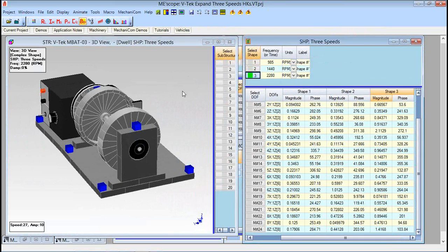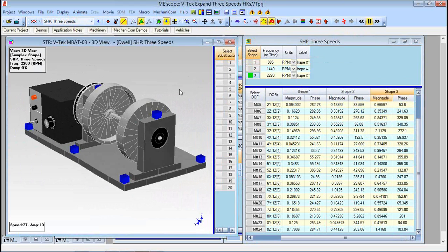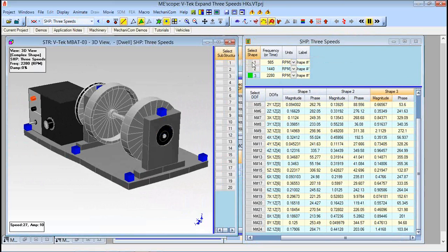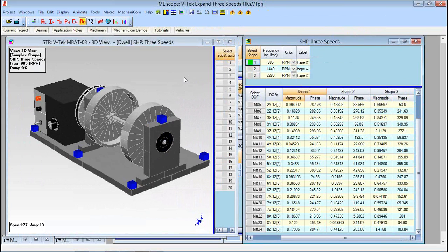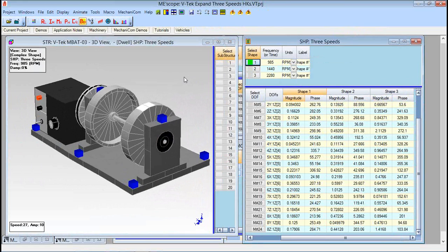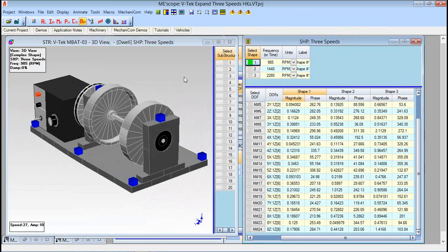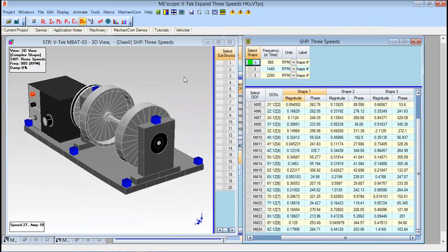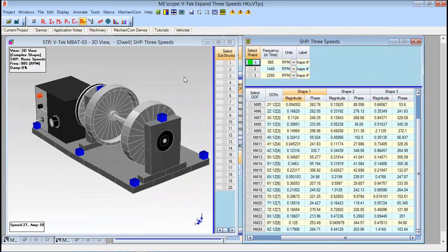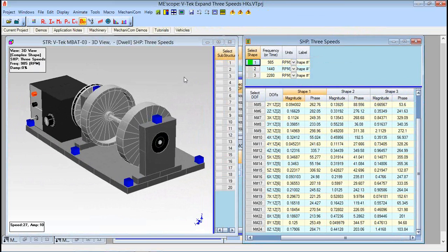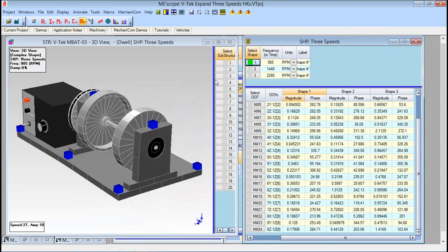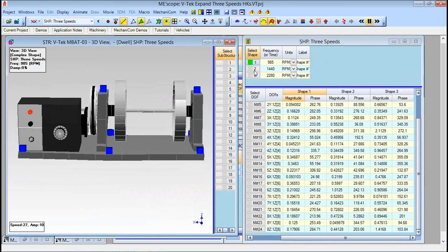Quite a different motion. There are 4 rubber mounts under the corners of this machine, and plus it was sitting on a rather flexible table. So the machine is showing a lot of rigid body motion simply because it's bouncing on the table and on the rubber mounts of the machine itself. So this is an ODS, not necessarily a resonance in there, although the assumption is that if there's any flexure in the machine itself, let's go up here a little bit higher frequency.